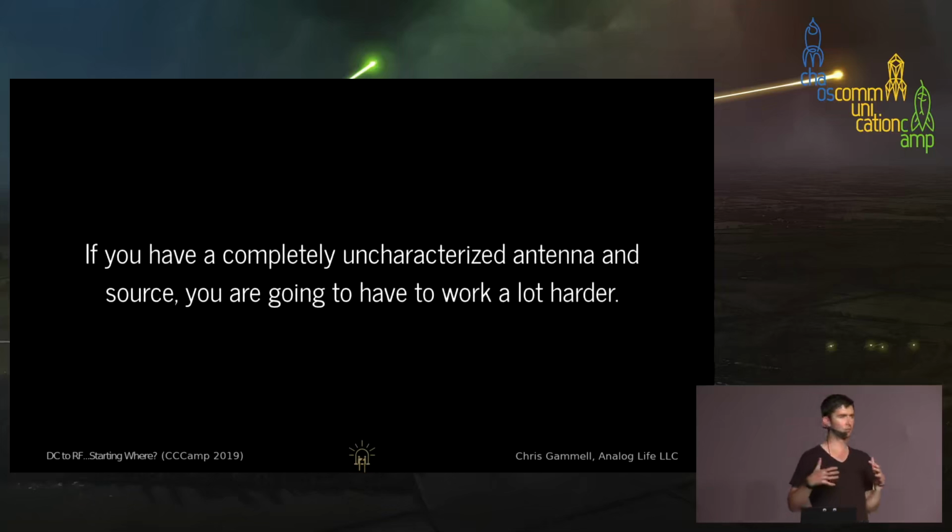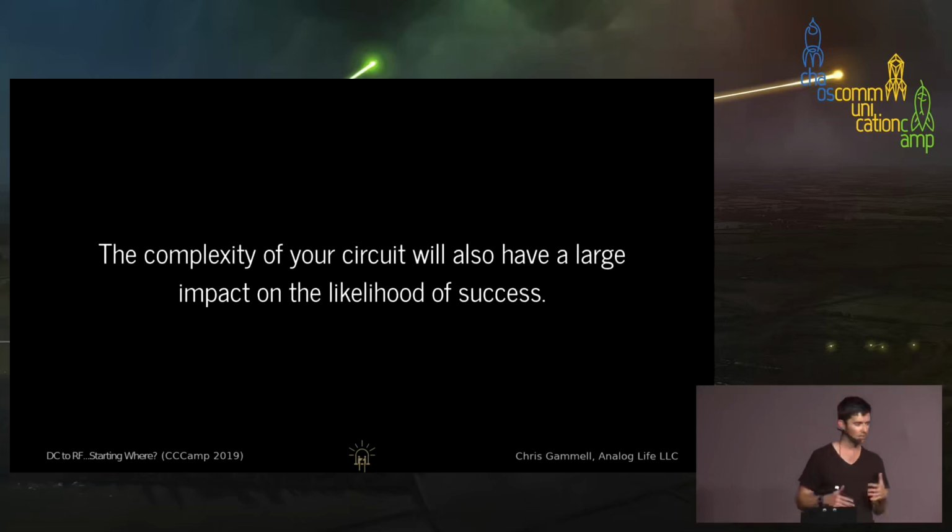When you're starting to move into a more uncharacterized zone, right? Say you want to make your own PCB antenna where the antenna is built into the board. That's going to be a little bit harder, right? You're going to need to do a little bit more characterization and testing. If you're going from a differential to a single-ended, you might have to do some more stuff there and do a bunch more math and use more components. But it's really the complexity of your circuit that's going to have the most impact on your success in that realm.